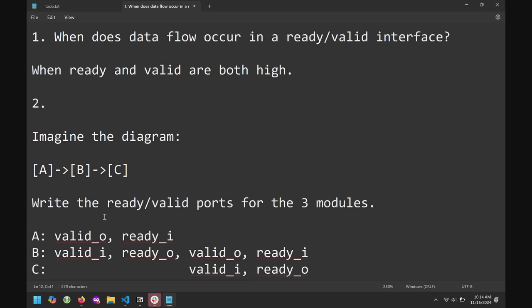So you are able to design your own circuit board. And usually you're probably limited to about 4 metal layers. You can get PCBs that have like 20 layers of metal in them, but for the most part, maybe you only have 4 layers. So if you want to route wires throughout your printed circuit board, it will go up through vias and snake around, but you only have 4 possible hierarchies that it can be at. It can't go continuously throughout the entire board. There's only 4 possible levels it can be at. Versus in chips, you will definitely have at least 20 layers of wires. You can have incredible routing capabilities through your chip.